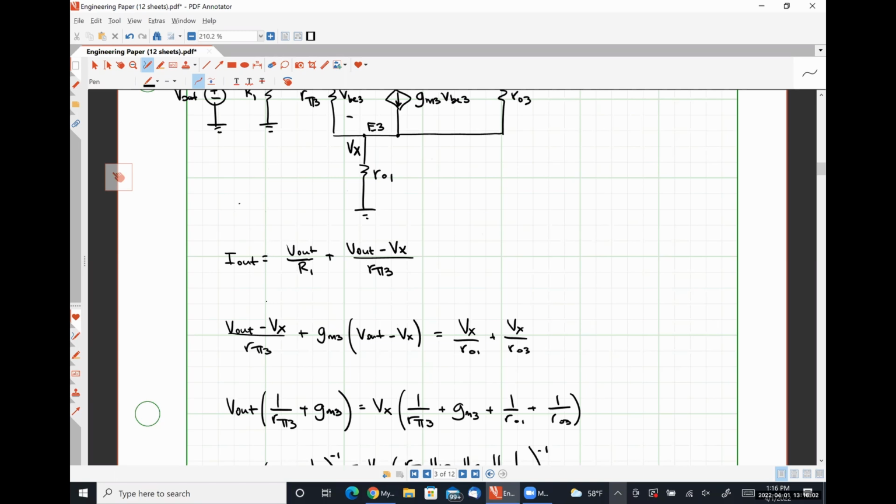For our common mode rejection ratio, we have a formula that's 20 log of the absolute value of A_V,D. What is A_V,D? That is the differential mode gain. I'm using bad notation. ADM, the differential mode gain. I apologize for that as well. So there's a differential mode gain, there's a common mode gain, and then there's a common mode to differential mode conversion gain, and they all represent different things because electrical engineers are assholes. D is for differential, C is for common, and I apologize for mixing up notations there. I've got to get more consistent.